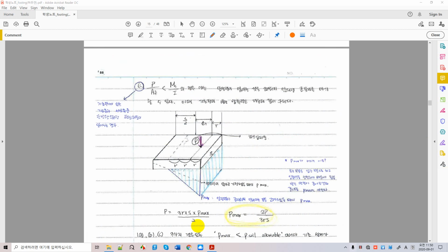Now let's take a look at a case where the stress due to the overturning moment is greater than the stress from the vertical load. There, as we saw already, we have a tension zone underneath the foundation, which makes the foundation cripple.